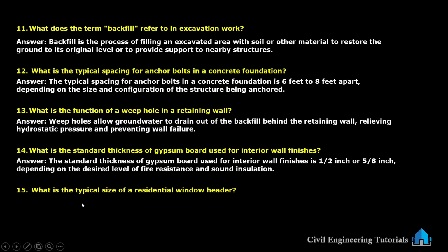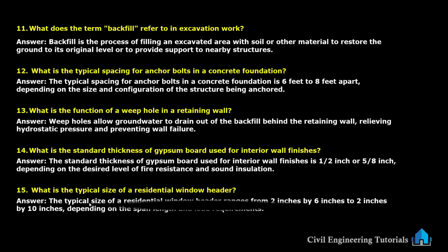What is the typical size of a residential window header? The typical size of a residential window header ranges from 2 inches by 6 inches to 2 inches by 10 inches, depending on the span length and load requirements.